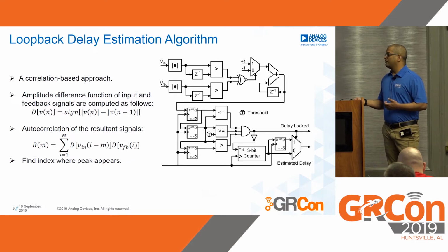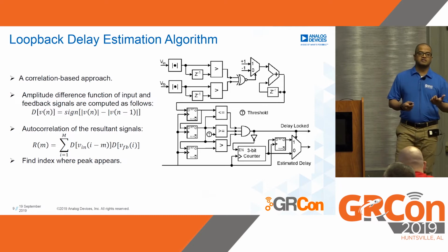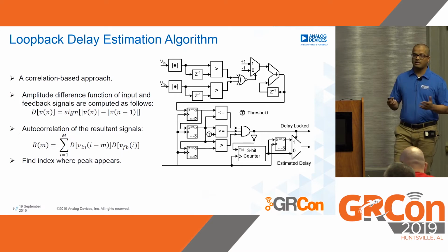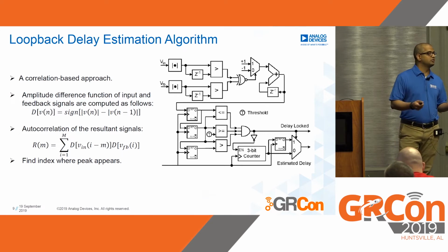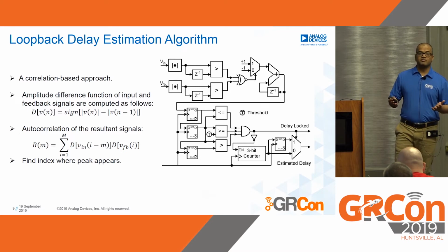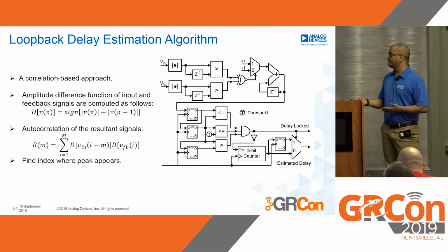And finally, what we have here is a simple local max finding algorithm. We feed a particular threshold, and it finds the local max and the index associated with that value of the correlation function to give us the value of the integer delay.